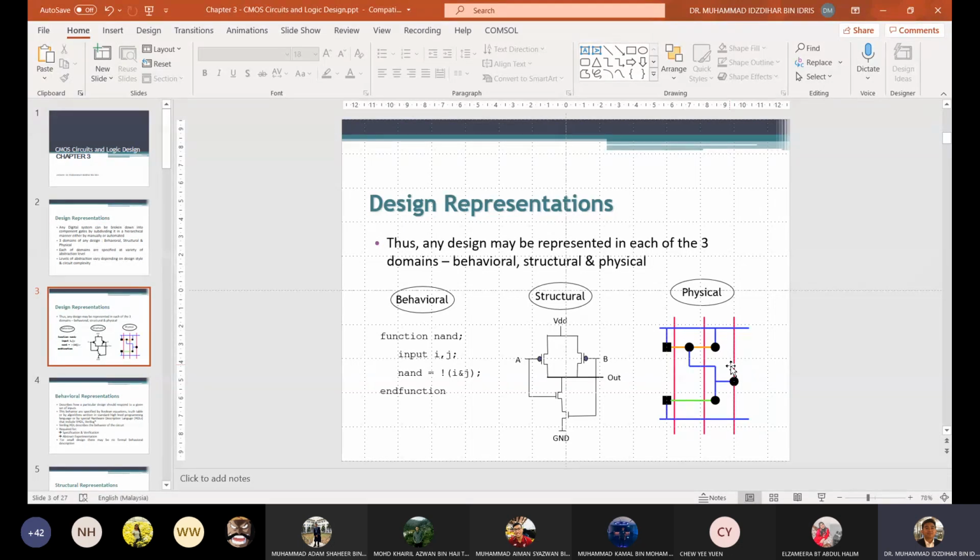So if you still need something less than 1 micron, you either use a different technology or a different machine, or you have to do something to make it work. We call this a stick diagram. When we have so many transistors to design, you can simplify using this stick diagram. In chapter 4, I think this is the main content for the stick diagram.